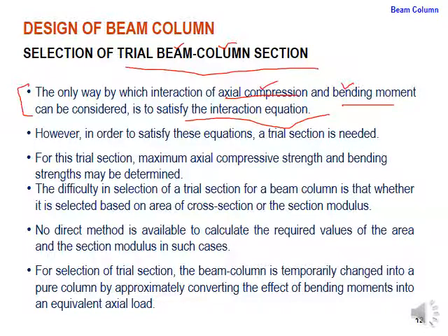However, to satisfy this design interaction equation, a trial section is needed. For this trial section, the maximum axial compressive strength and the bending strengths may be determined.